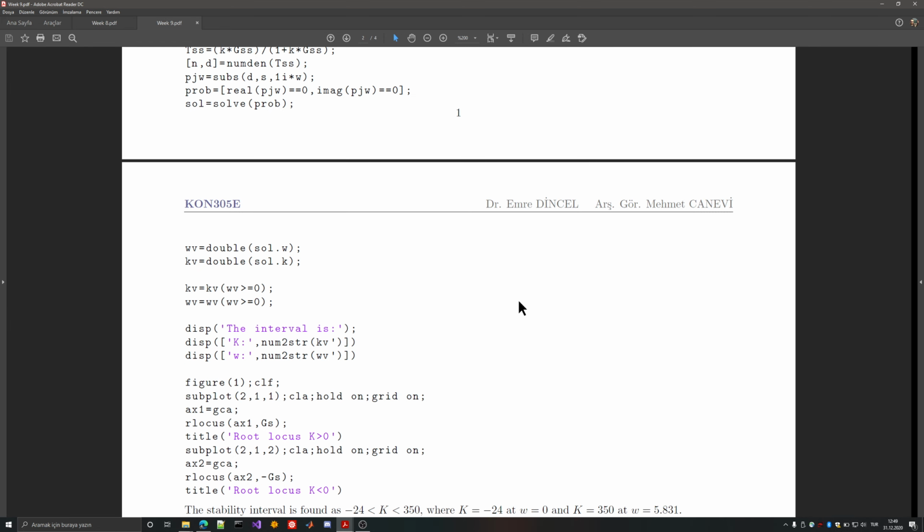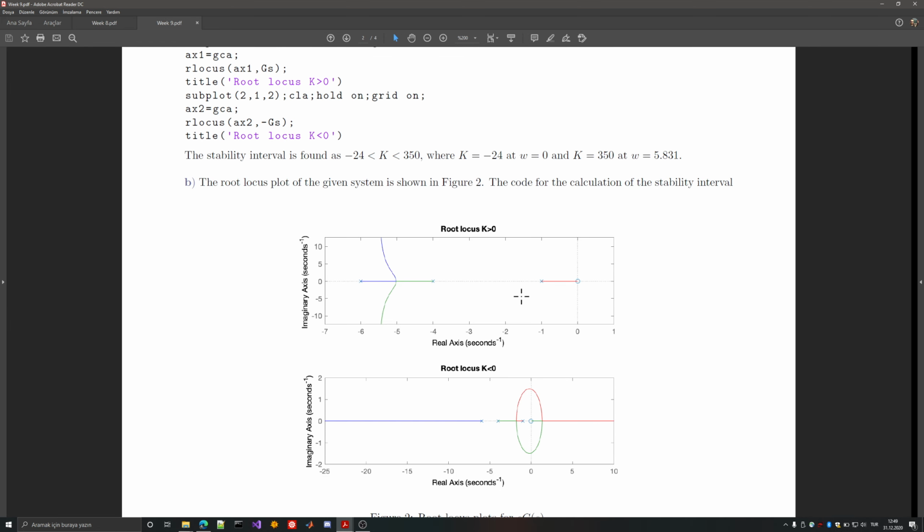So basically, the whole movement will change, and since this ensures that one of the poles will approach the zero, I'm basically preventing the crossing of one pole. So it is easier to contain two poles on the left half plane than three of them, because of the angle condition and the asymptote angles.